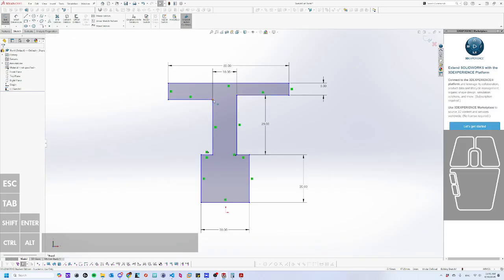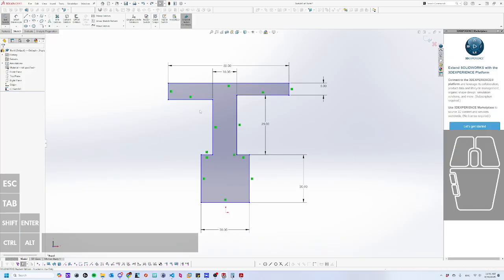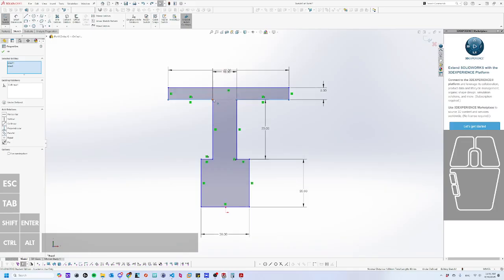But I think if I did it for the endpoints, because they're already set as horizontal lines, if I select the 2 points instead and make those horizontal, it'll line them up. The safer option though, in this case, would be to hold down control, select both lines, and make them collinear. So this symbol means that it'll line them up and it'll connect them by this dotted line that isn't actually part of the drawing. Okay. So this looks relatively good.